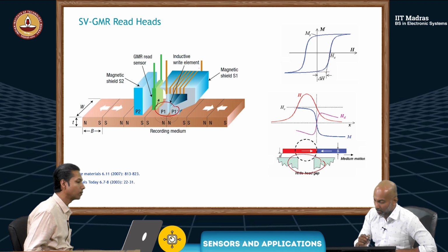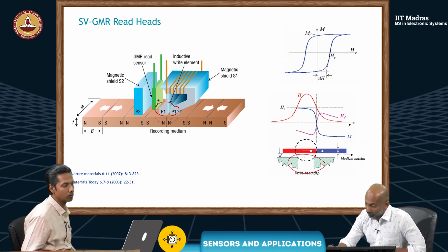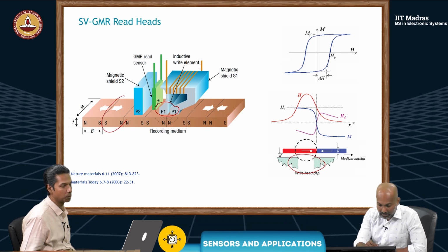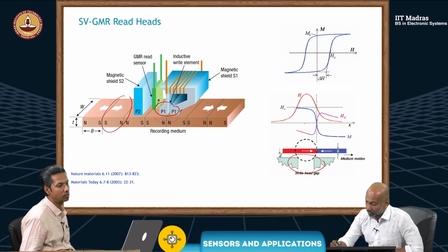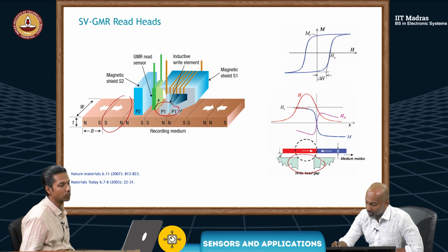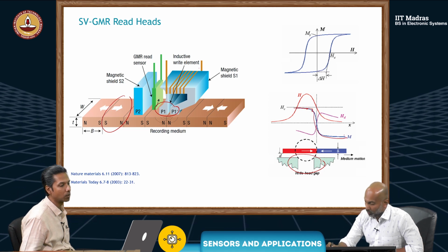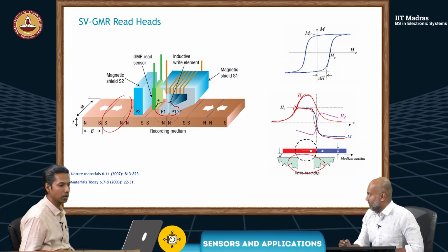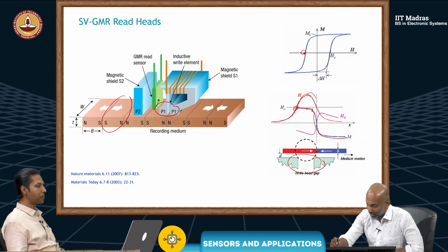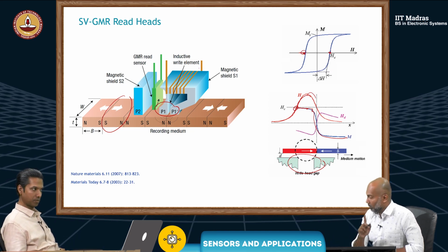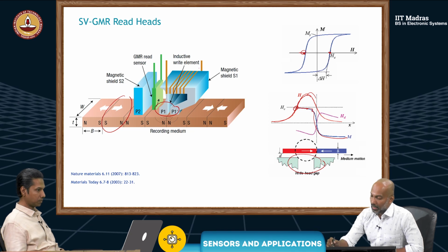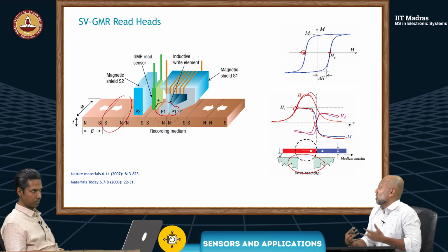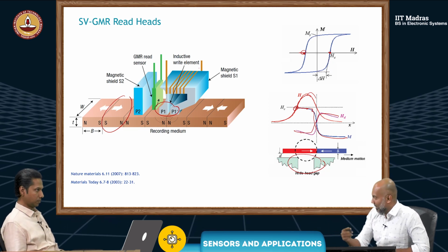Then you want to switch the magnetic domain of one of these sections. Let's say it's in the positive direction now and it has to go to a negative direction. The applied field must be higher than the coercivity. Then you have what is called the demagnetizing field. When you have a certain magnetization, there will be some opposition to it. That's what is shown here.